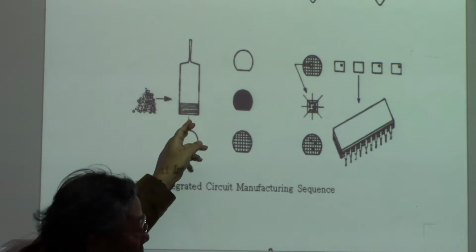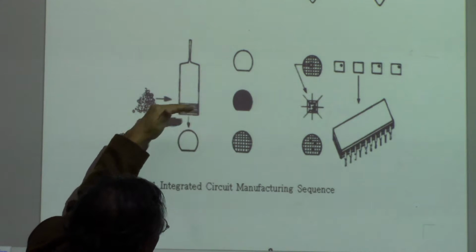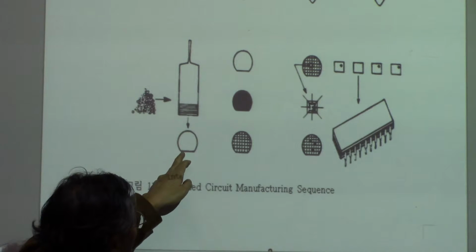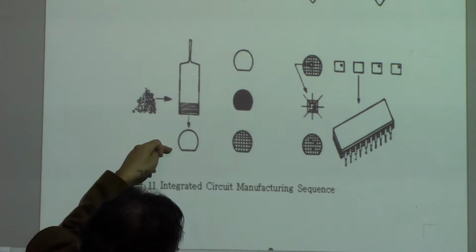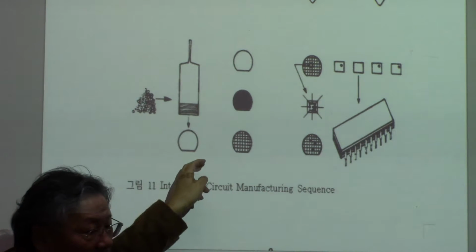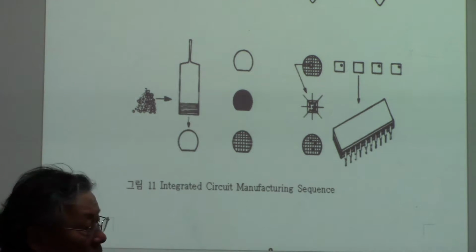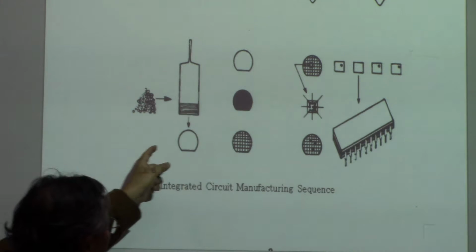We grow the single crystal and then we cut it in vertical sections, right, to make wafers, which is shown like here, and then we identify whether this silicon single crystal is N-type, P-type, or 111, or 100, or 110 directions, things like that, okay?